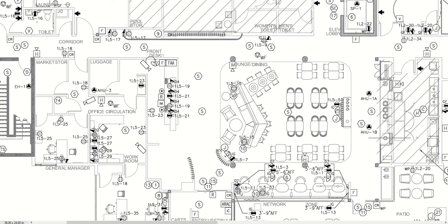So if you have them every 12 feet, no matter where you put whatever it is you're plugging in, you should be able to reach an outlet location. But that rule doesn't apply to commercial work, only residential areas, which we will have on this project. But in the commercial areas, there's no real rule for spacing, so we just use common sense and experience. So like in an office here, you're probably going to want at least one outlet on each wall. And we'll try to be cognizant of where the furniture location is, or desk. So we put one for the desk.